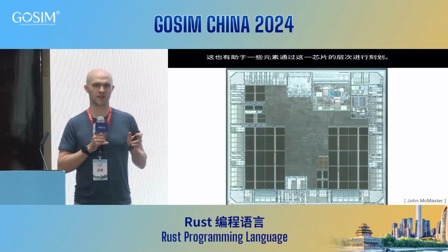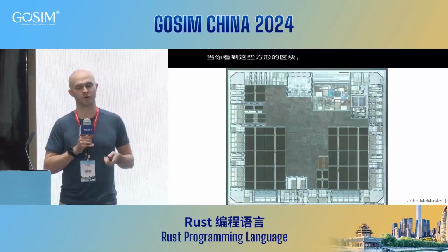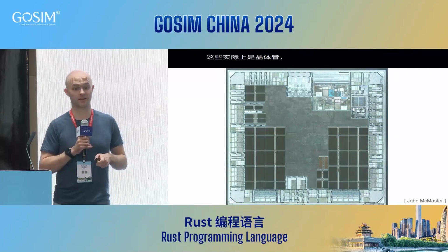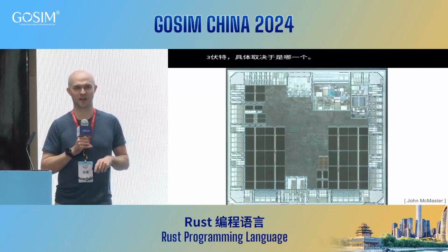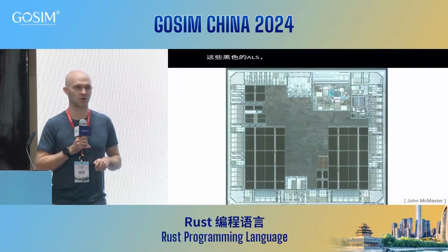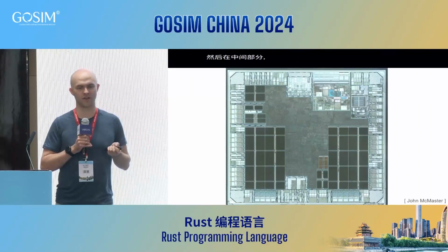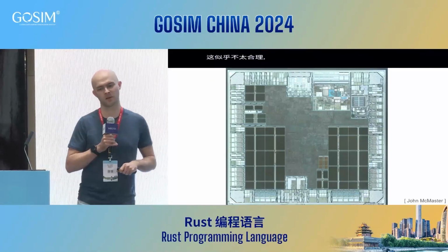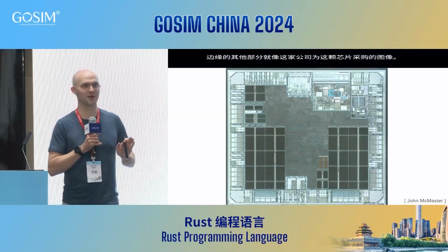And these are actually the transistors pulling those copper lines either down to 0 volts or up to 3.3 volts, depending on what your voltage is. We have these black areas, those are the memories, the various memories in this chipset. And then in the middle, we have this entire spaghetti part of transistors, which does not really seem to make sense, but it's actually auto-generated, synthesized, according to the definition of the vendor. All the other parts on the edges are like images that are bought in by the company that made this chip. As an aside, who knows what chip this is from purely the image?